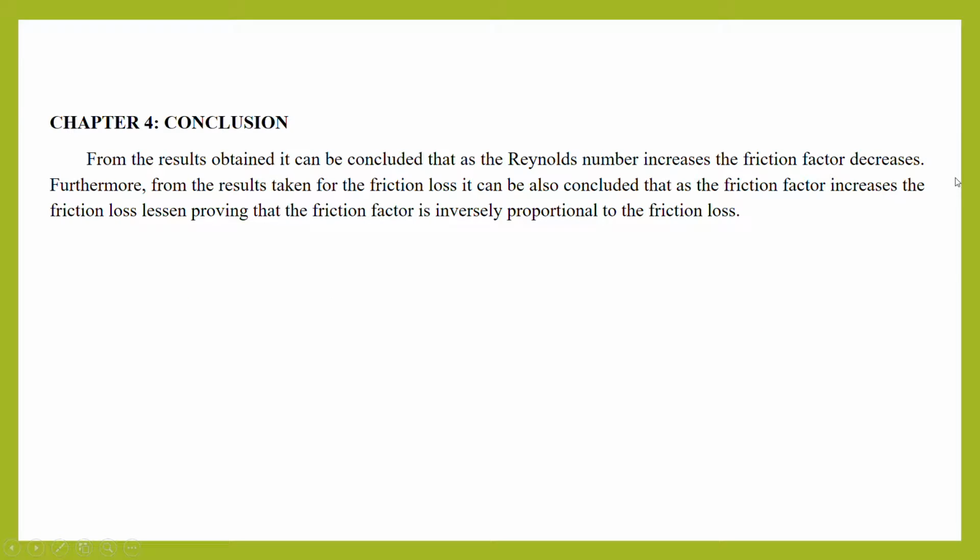Concluding our presentation of our lab Experiment 10, from the results obtained, it can be concluded that as the Reynolds number increases, the friction factor decreases. Furthermore, from the results taken for the friction loss, it can also be concluded that as the friction factor increases, the friction loss lessens, proving that the friction factor is inversely proportional to the friction loss. Thank you.